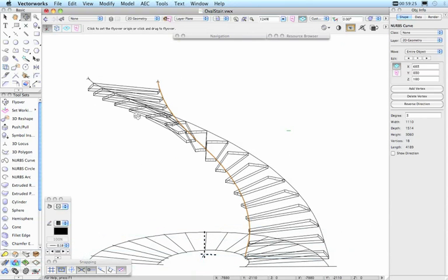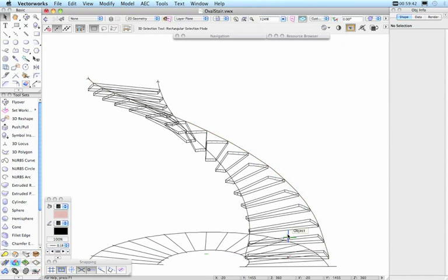But if you didn't get a point right, if you double click either of these curves, you'll see that there is a control point at each of these, and you can just literally move it up and snap it onto the right point to get the curves looking or snapping properly. Alright, we don't need these 3D loci anymore, so we can delete those. Alright, now this is where it gets interesting.